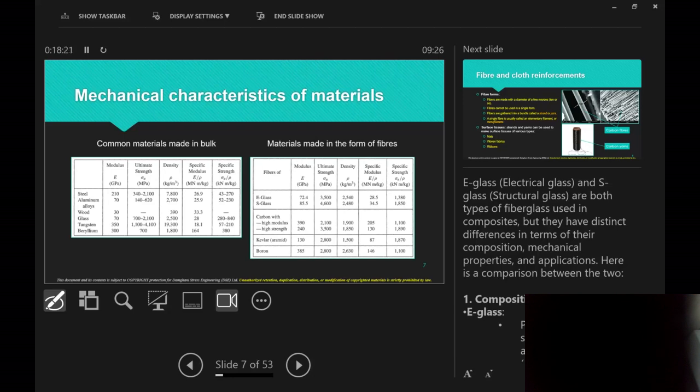If you look at the glass, we're talking about 1,380, 270. Six times as much, almost. Six times as much as steel. If you look at carbon, high-strength carbon, that's the one we use for aerospace, 1,800, let's say 2,000. It's not even comparable with what you get here. So that's the specific strength that we really value when it comes to composites.